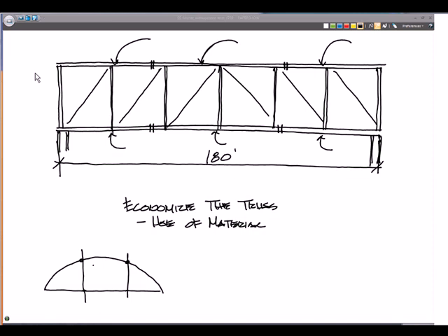So maybe for this middle piece, I'm going to use a heavy W14 member. So we can write in here, maybe it's a W14 by 211 like we had for that column. And we can use that at the top and the bottom, even though they'd probably be different.